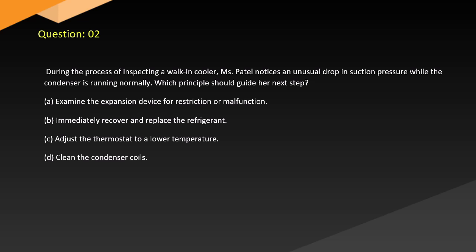Question 2. During the process of inspecting a walk-in cooler, Ms. Patel notices an unusual drop in suction pressure while the condenser is running normally. Which principle should guide her next step? A. Examine the expansion device for restriction or malfunction. B. Immediately recover and replace the refrigerant. C. Adjust the thermostat to a low temperature. D. Clean the condenser coils.